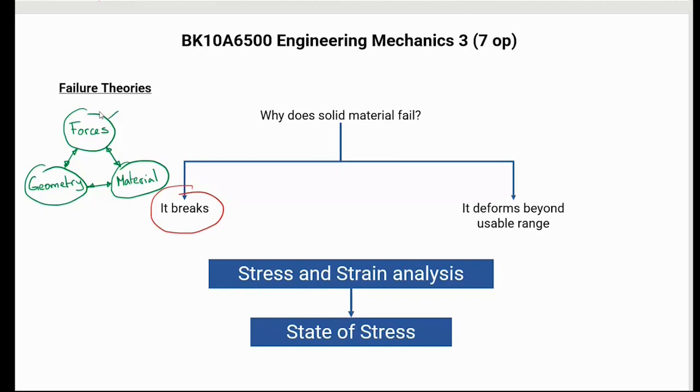In this triad, forces are something that you might not be able to change, because those are the forces that the part needs to resist, the machine element needs to work with. So maybe there is no change here. This is something prescribed, so it's already existing. Because when somebody asks you, can you design this kind of part, you start searching for what the loads are that are going to be applied there. What are the forces that the part needs to withstand? You take that as a very fixed input that most likely you are not going to be able to change, but you have to be conscious that they might be more deleterious or damaging than you are considering. So you always have to think the worst when talking about forces.